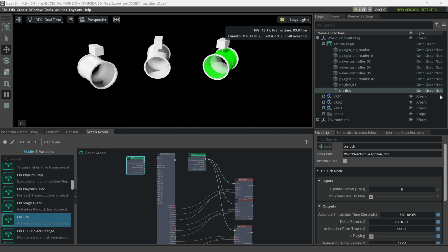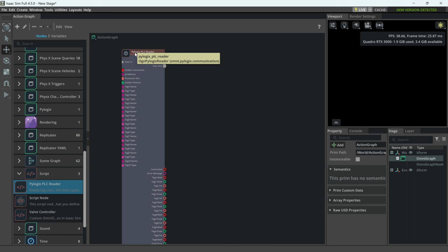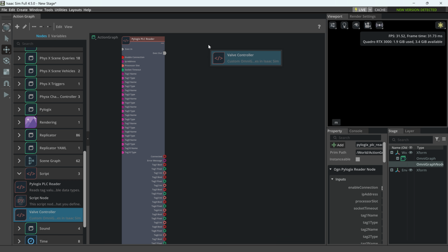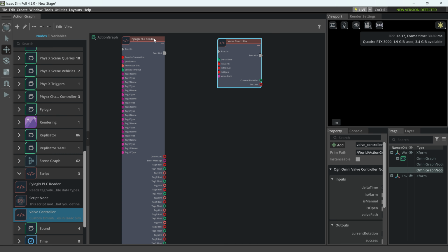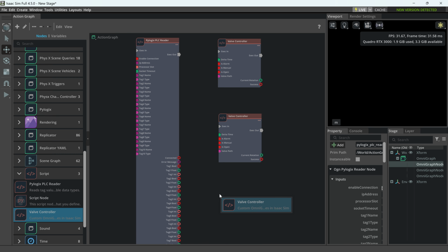Can a visual valve behave like a real valve without custom scripting for every instance? That's what we are doing in Sim. In Sim, I imported 3D valves and connected them to a PLC through a small action graph. To read from the Micro850, I used a small Python library called Pylogix.